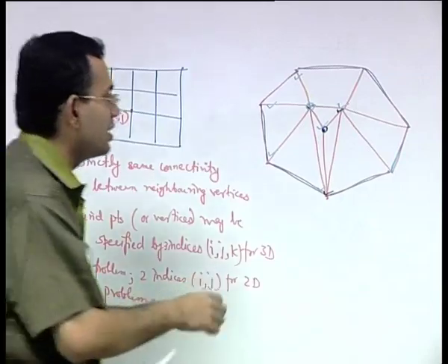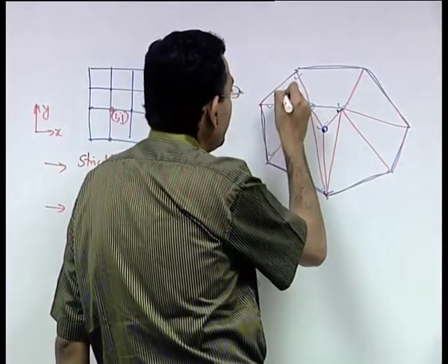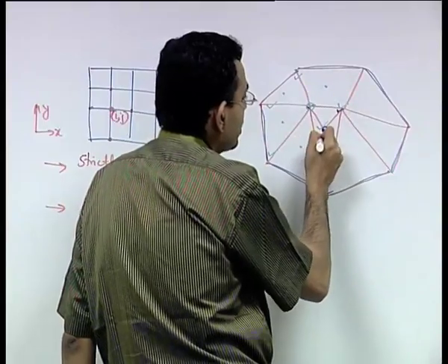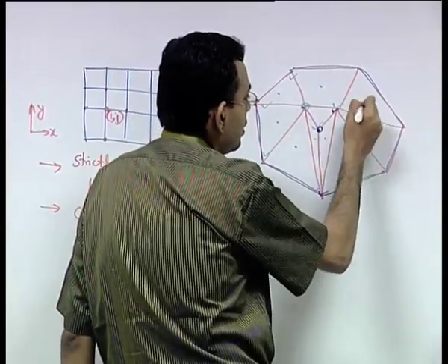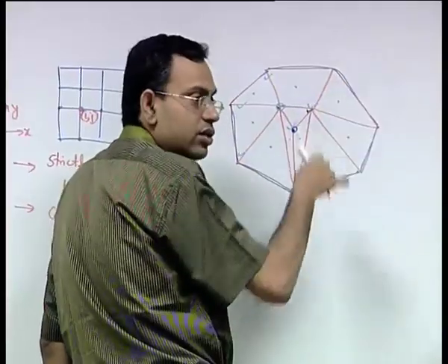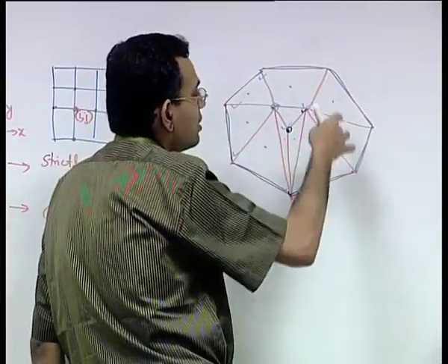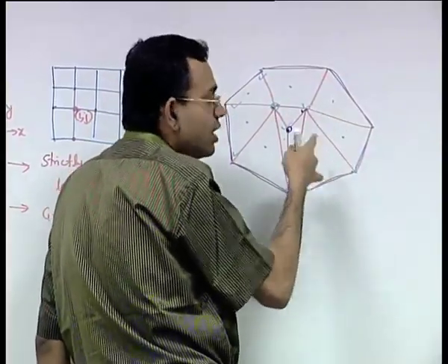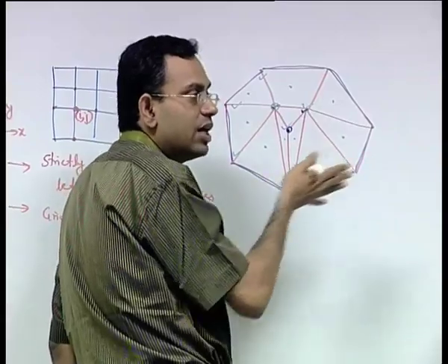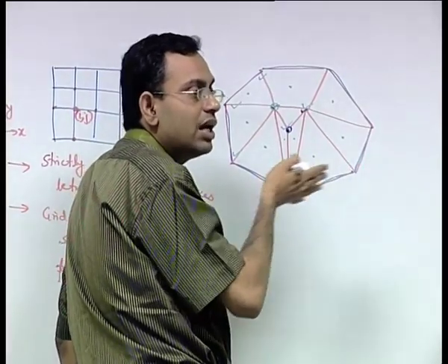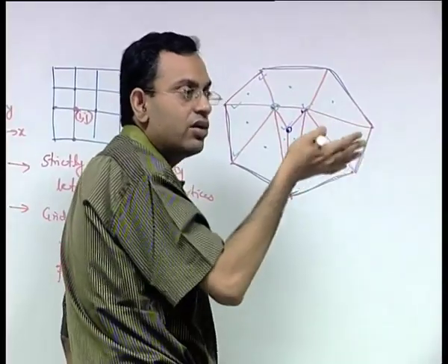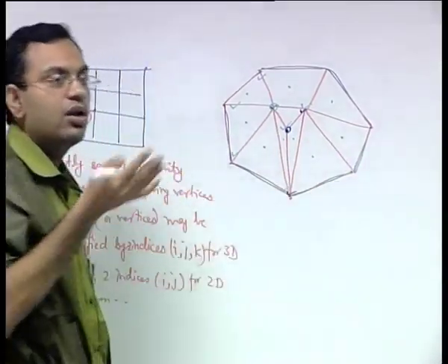Not only that, see the grid points which may be representatives of each of these control volumes, say the centroids of each control volume. They are located at arbitrary locations in space in a way that you do not have them located on particular laid out grid lines, neither along x nor along y nor along z.